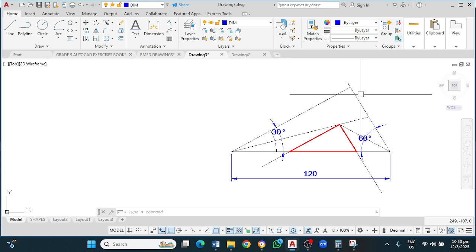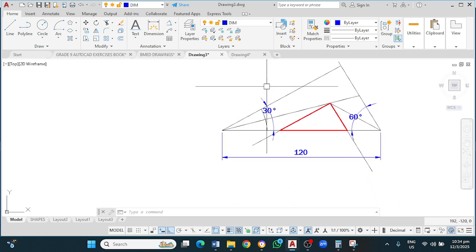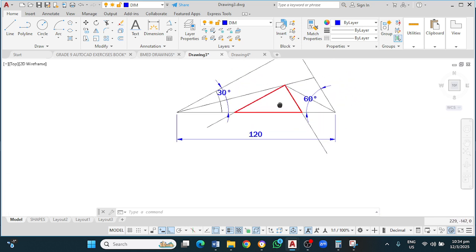Our next task under triangle is to construct a triangle. We construct a triangle ABC when given the perimeter and the ratio of the sides. So number 11 is to construct a triangle when given the perimeter and the ratio of the sides. In this case, just a reminder that we are at chapter 4 in Master Technical Drawing, Plane Geometry. Okay, plane geometry.